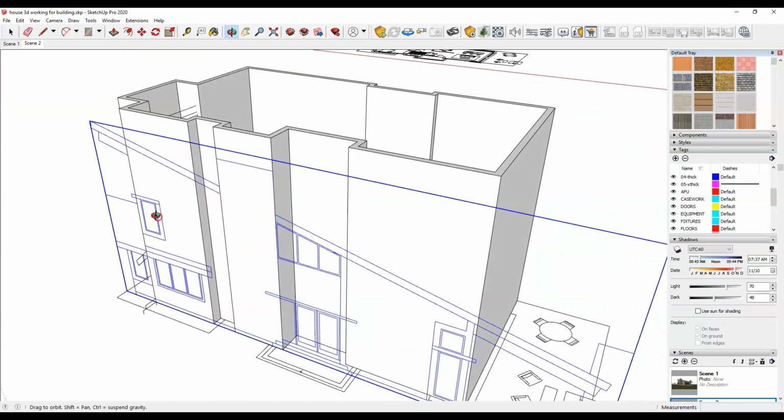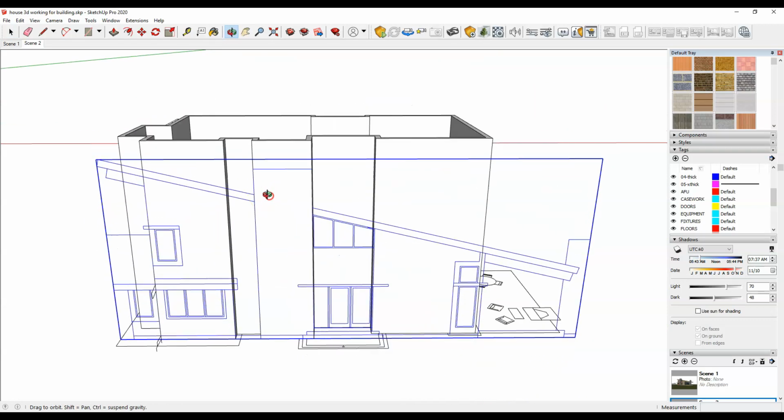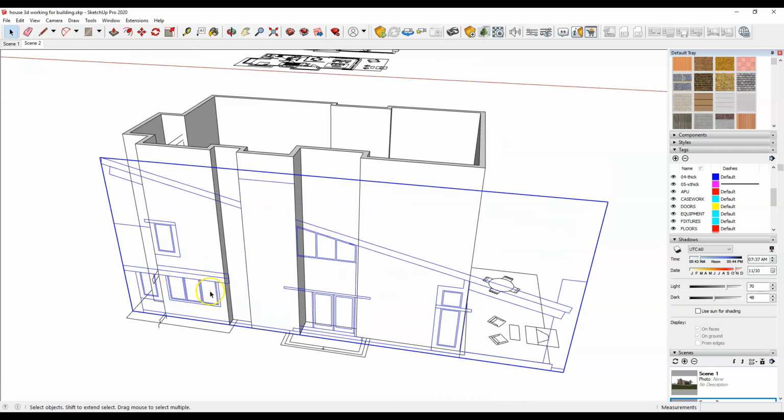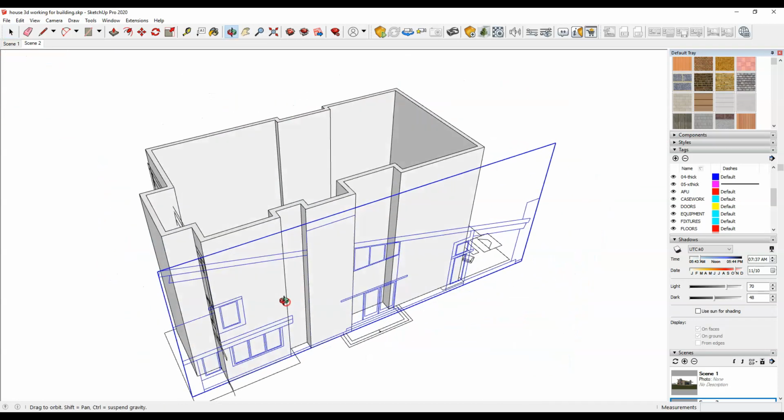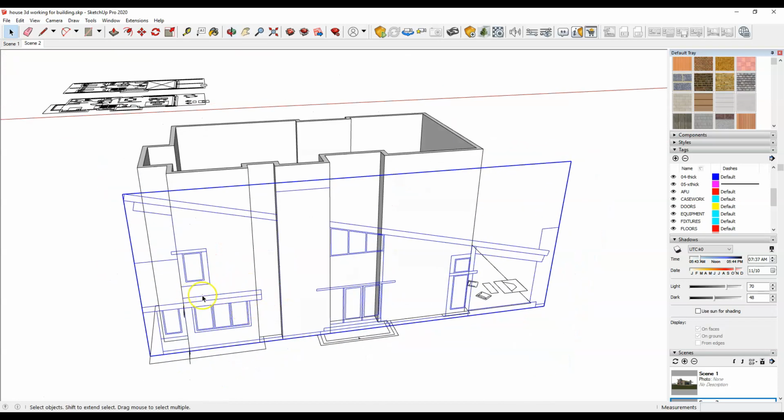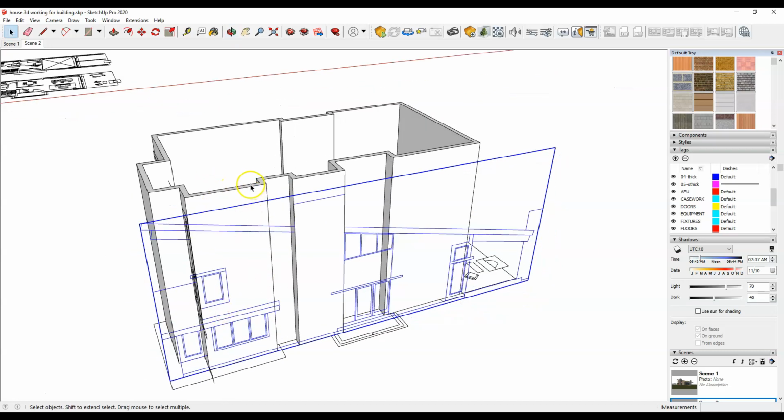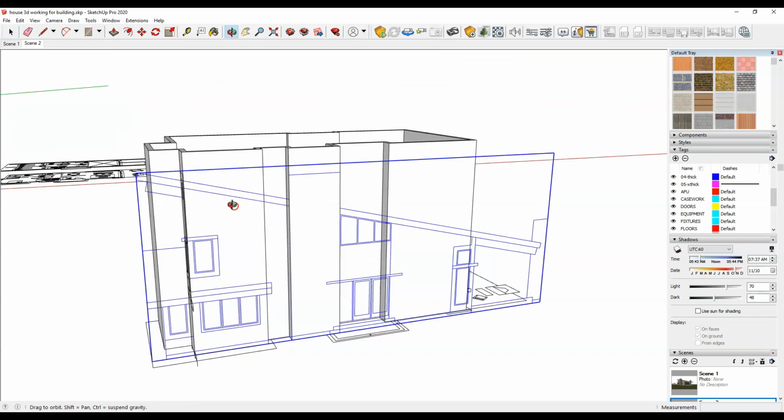Now be careful if you're working on this house. This is a trick in here. This corner is tricky because this is out here on the first floor, but this upper floor is actually at this level. So if you were smart, you'd draw a line right here now and push this surface on this upper level back into this plane. That's just a heads up tip.